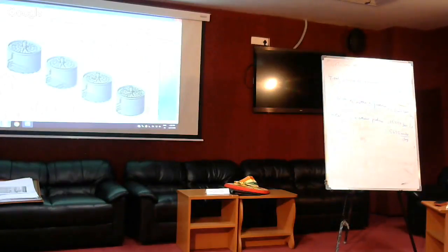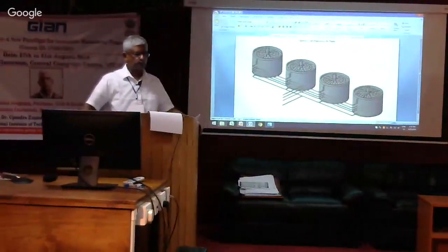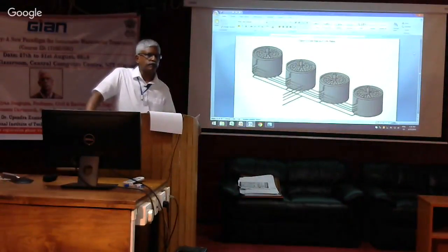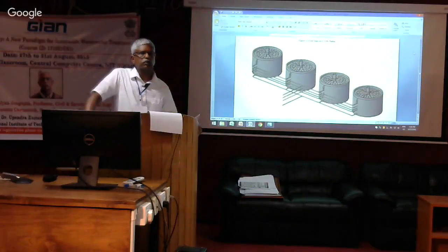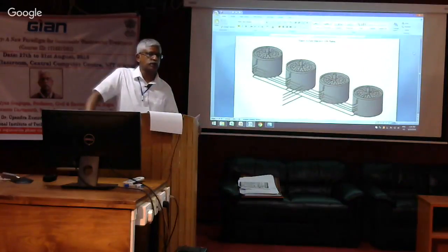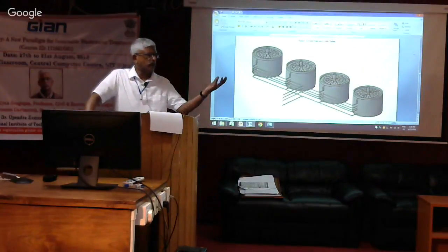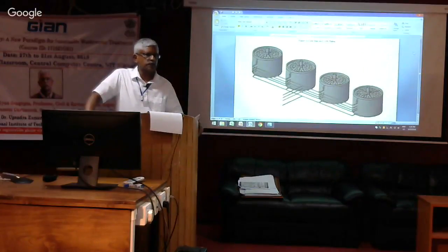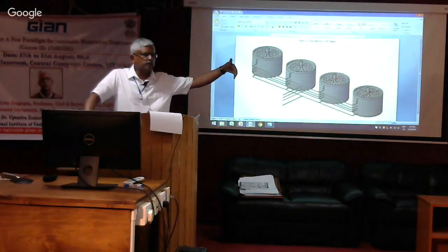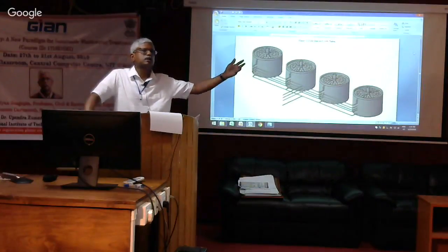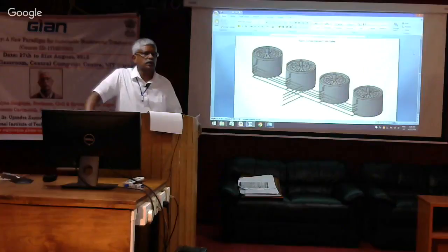Here you used only the stoichiometric equation, only methane and oxygen. Suppose it is a heterogeneous system, so there may be methane or any other compound, glucose also may be present. At that time, what will I do? With the stoichiometric equation, glucose will also be converted to carbon dioxide. So as long as it is being completely oxidized, it doesn't really matter what you're starting with, because we are looking at the oxygen equivalence, the oxygen demand. So we didn't even know what is the constituent of this brewery waste. It's not really important.